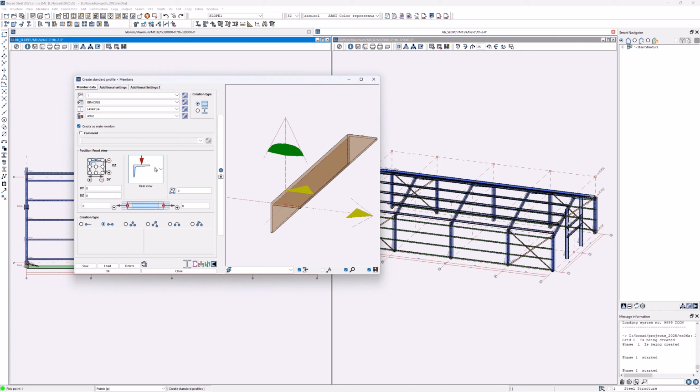And we'll say the first bracing will be created with the last position we have here. Rear is fine. We give a little offset of 3/16. Now, if I create it now, 3/16 will be at the same plane as where we pick the points. That is not bad, but we will be on the top flange.